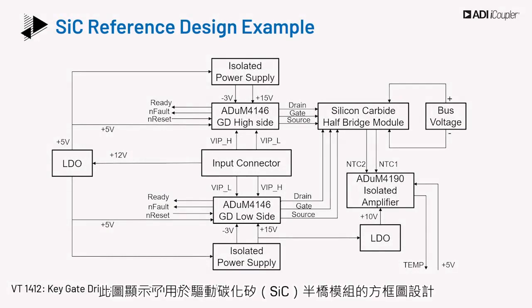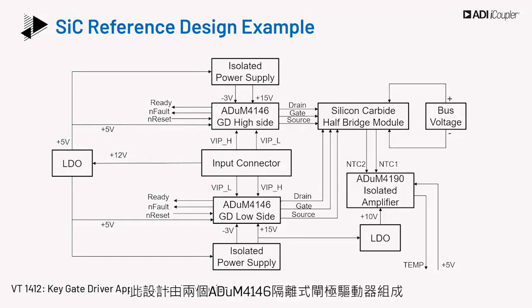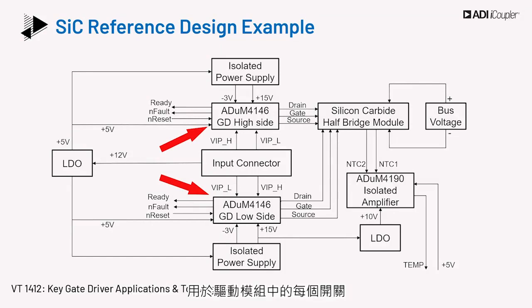The figure shows a block diagram design for driving a silicon carbide SiC half-bridge module. This design consists of two ADuM4146 isolated gate drivers to drive each of the switches in the modules. The ADuM4146 is a protecting gate driver with bipolar supply, Miller clamp, and desaturation protection.